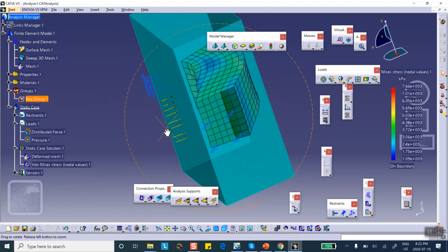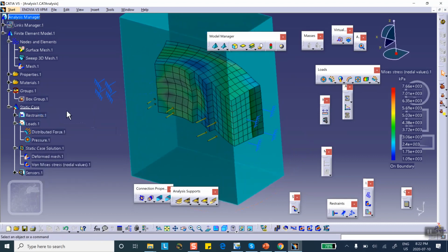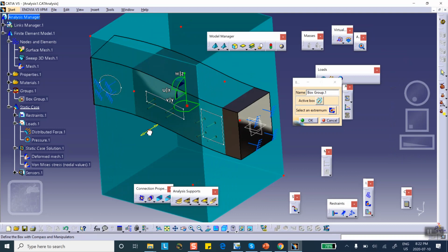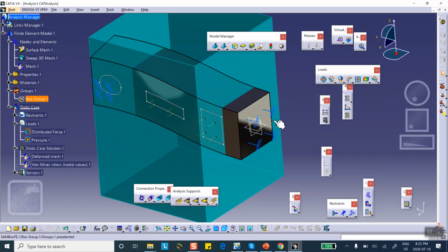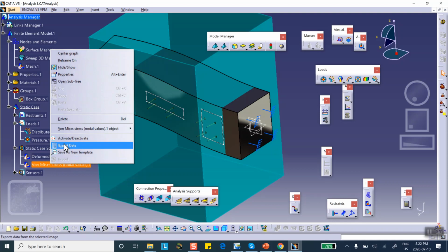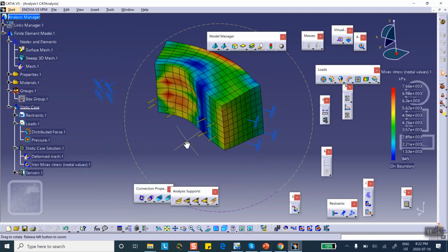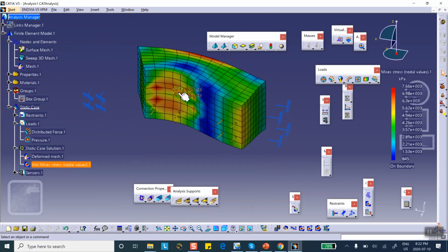Okay, so notice that I did cut off some of these things. So double click on it, resize it, grab this and make it go this direction. Okay, so it's covering more area now, and deactivate this and hide it. There. I promised that there was a red blob here because you're applying 5,000 Newton. That's a lot of force, but we couldn't see it because of these clamps taxing the rest of the structure.